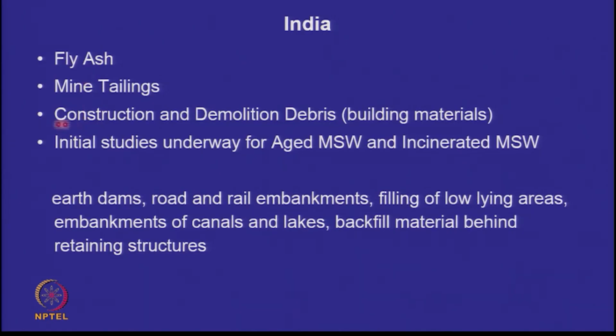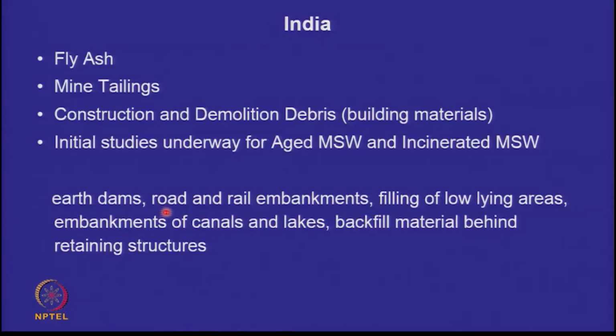Important. We can use construction and demolition debris, but we have to process it, we have to crush it and bring it to workable size. And initial studies are underway. Can we use old municipal solid waste or incinerated municipal solid waste for geotechnical reuse? And we are talking of earth dams, road and rail embankments, filling of low-lying areas, embankments of canals and lakes, backfill materials behind retaining structures.